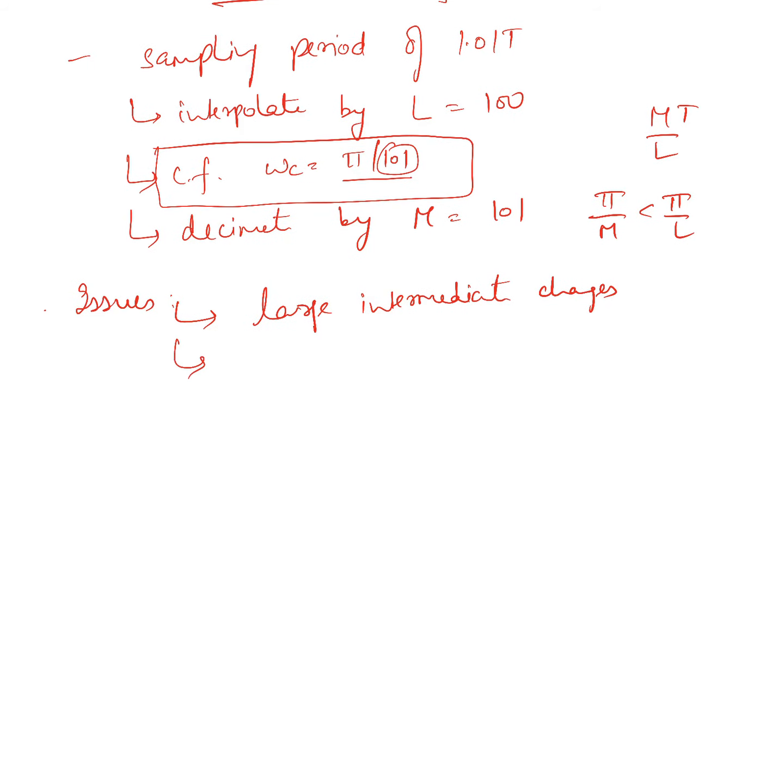The second issue is that a large amount of computations for each output sample is required. So seeing these two issues, we aim to reduce the amount of computations first of all, and this we can achieve by the concept of multi-rate signal processing that we are going to discuss.